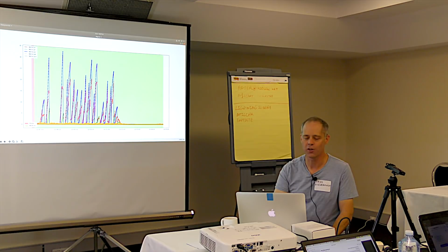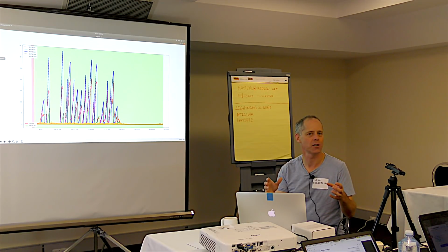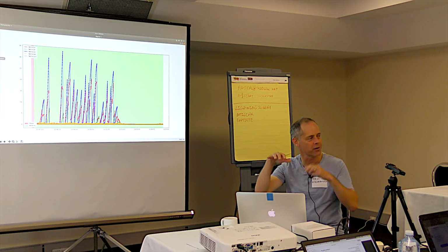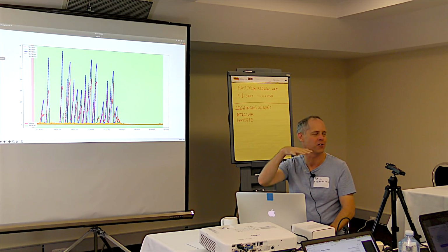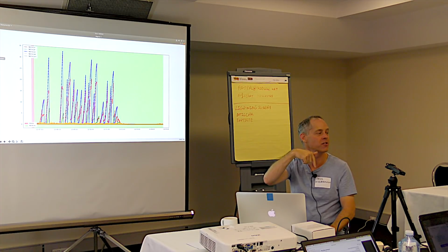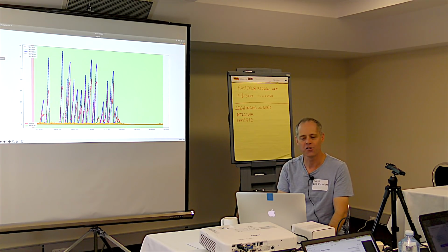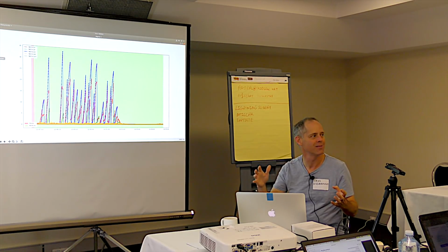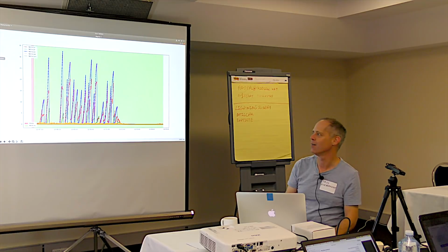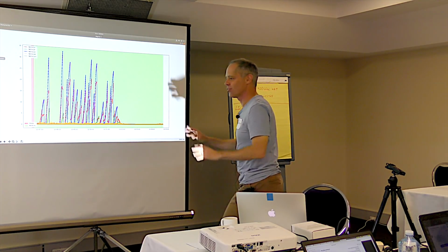Because what happens when you have clipping on your vertical accelerometer is the accelerometer is measuring 1G. When it starts to clip, instead of measuring 1G, it squeezes the average acceleration measured towards 0, right? So the accelerometer measures 1G, or minus 1G because positive is down with the accelerometer. You put a lot of vibration in and it starts to clip. It squeezes the average value to 0.